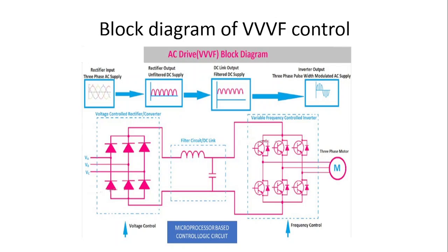Then between the floor levels it has to move at a constant speed, and when it approaches the next floor level, it has to decelerate and stop at the particular floor level without any millimeter level change in the floor level. So that is the basic requirement of an AC drive in case of an elevator application.